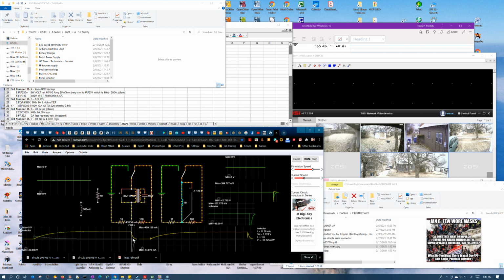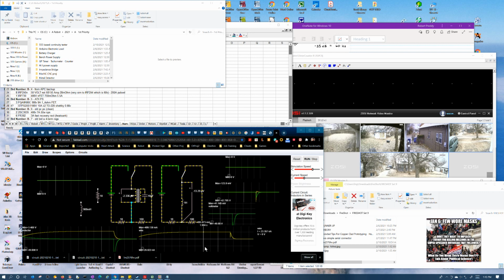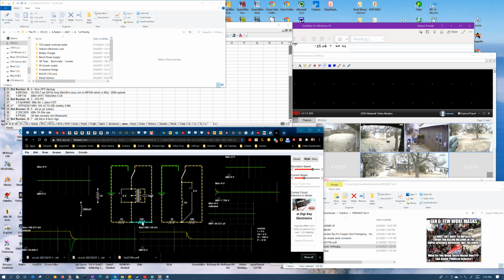Okay, the current drops much more slowly now, and the voltage difference is not nearly as high. The same thing kind of applies to this. This damped out really quick. We saw a little blip here because of that capacitance, but it was nothing like it was before. There's certainly a little oddball kind of waveform here, but overall it dissipated that pretty quick, and that's because we had a smaller resistor here.